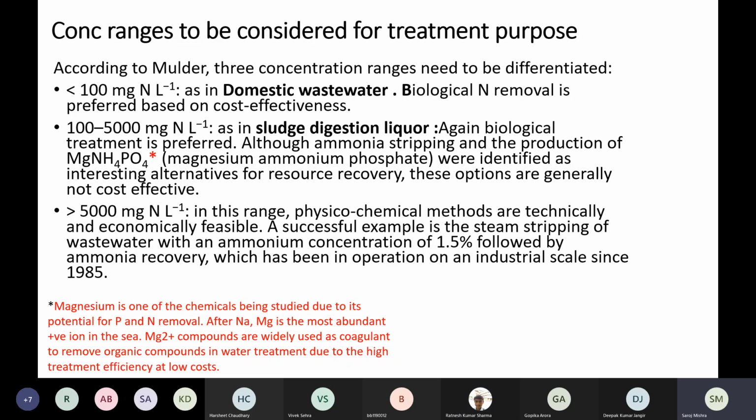Yes, ma'am. Okay, so I think let's stop. We are talking about nitrogen in waste, right? Nitrogen which is coming in the wastewater effluent now. Yes. Because it still contains a lot of nitrogen, because we will see the biochemistry of the activated sludge is such that it is a completely aerobic process. Whereas conversion of nitrate into free nitrogen gas must occur in the absence of oxygen. And that is why denitrification cannot occur in the activated sludge plant.